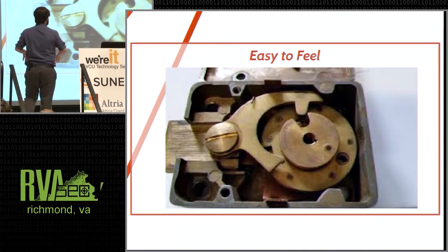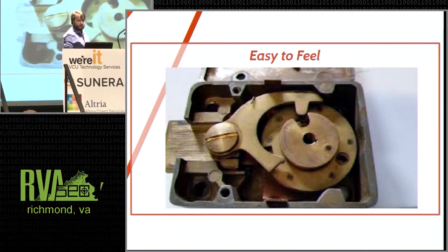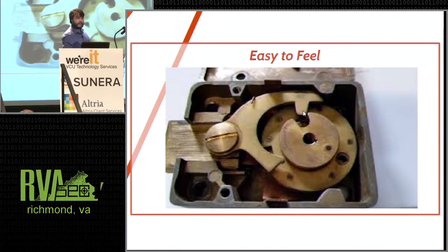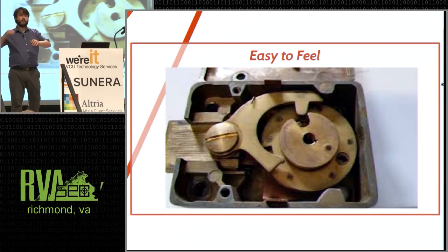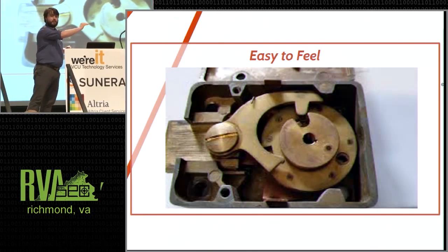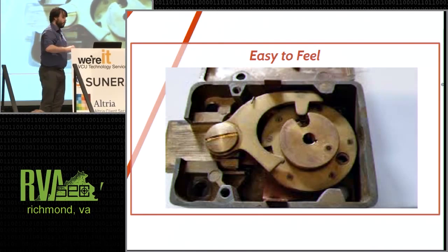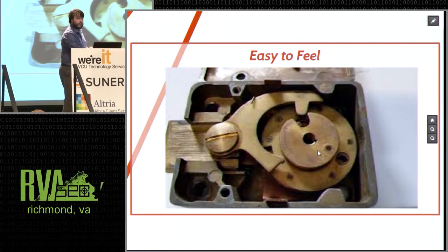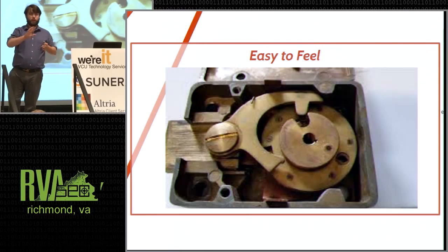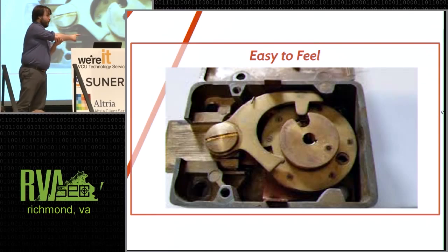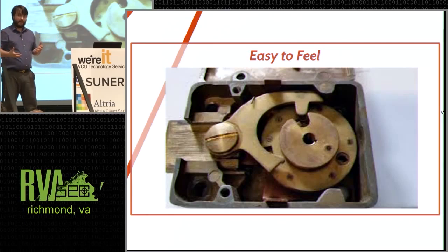Cool. So they invented what's called the nose. The nose is this little bit right here. Now the nose is connected to the fence. The fence runs over the top of all of the tumblers in the lock. The nose is riding on this wheel back here, this smaller wheel, and that's called the cam wheel. The cam wheel is actually the one that you're controlling when you're dialing the dial. There's a post running all the way through to it, and that's the one that you're manipulating.